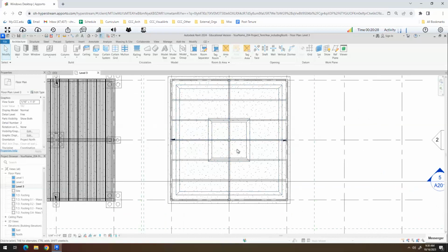We're going to be adding flat roofs to all of these, or they're already structured as flat roofs or low slope roofs. When we say flat roof, it's not completely flat. It's going to have a slope to it. Typically, when you have a low slope roof, you need to drain it, and there are two places that you can locate the drain.